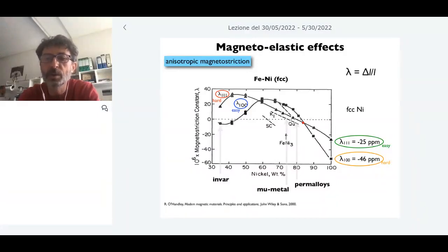If you don't want your magnetic material to be dominated by the stresses, then you need to use a material with very close to 0 magnetostriction. Permalloys are materials that can be prepared as thin films, and their magnetic properties maintain their soft character regardless of the strains that are imposed by the substrate. This is an example.